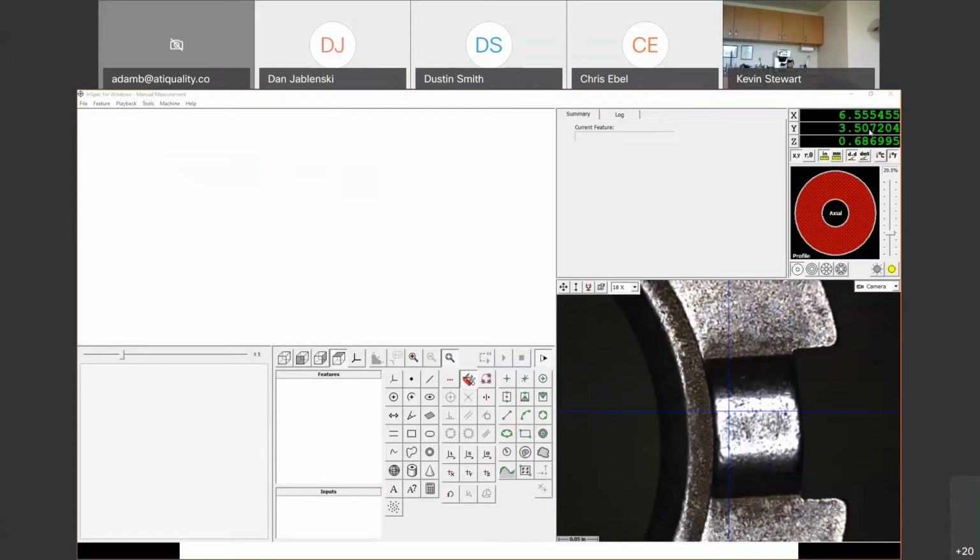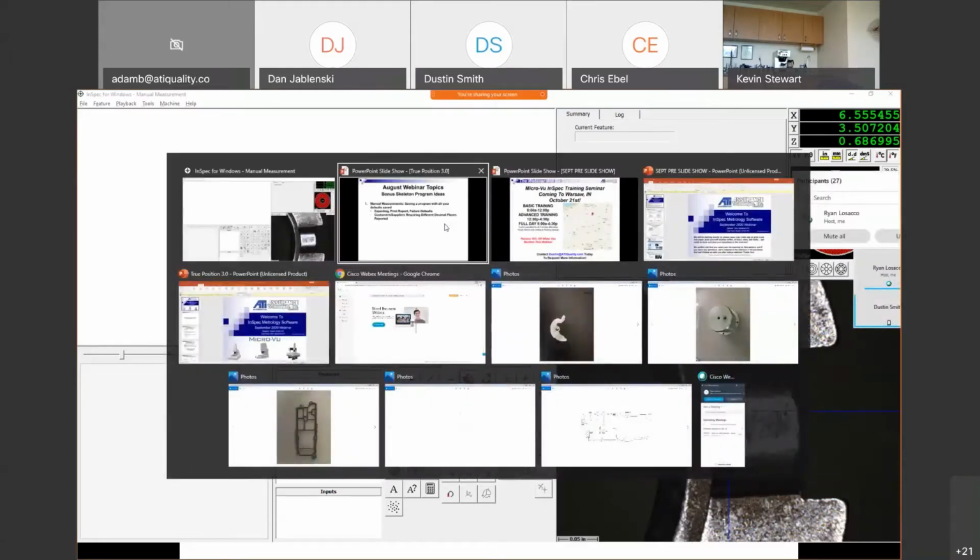One customer they had wanted 3 decimal places for inches. So they would have to go into new program defaults and a couple other things to change the decimal places every single time. But if you save a program of just 3 decimal places and a program of just 5 decimal places, whatever it might be, then you don't have to go and change that every single time. So just kind of little tricks there, instead of having to do more work than you have to every single time. Just wanted to throw that out there.